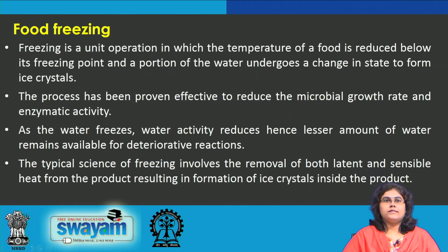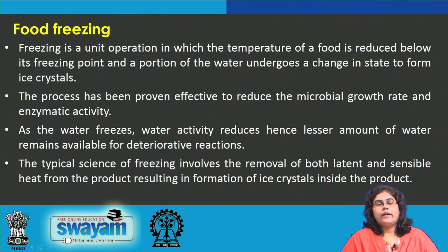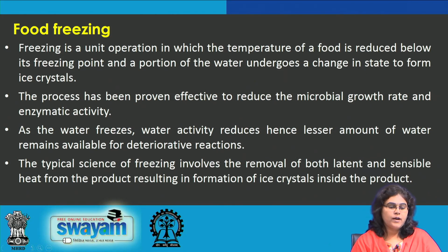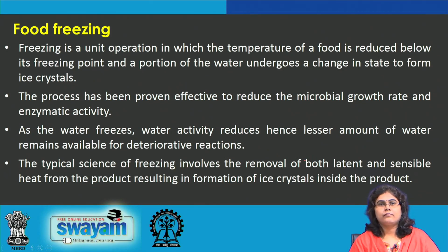Now coming to food freezing, we all know that freezing is a very important unit operation in food processing, in which the temperature of food is reduced below its freezing point and a portion of the water undergoes a change in state to form ice crystals. Due to the lowering of the temperature, the water activity of the food reduces, and due to the lesser availability of water in the food material, some of the deteriorative reactions are also reduced.